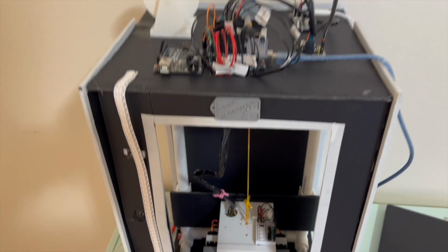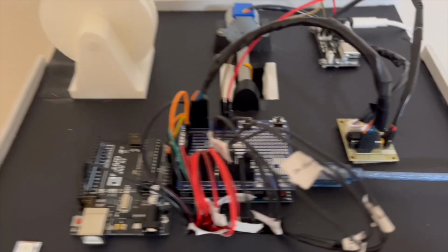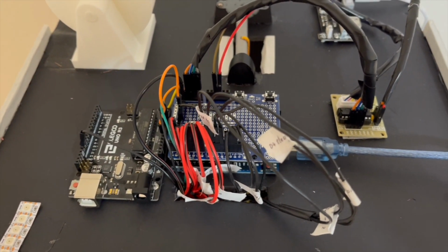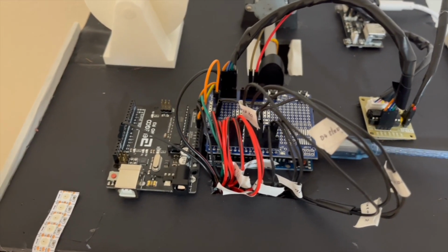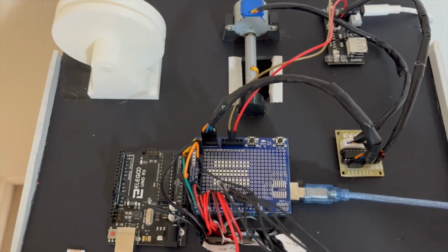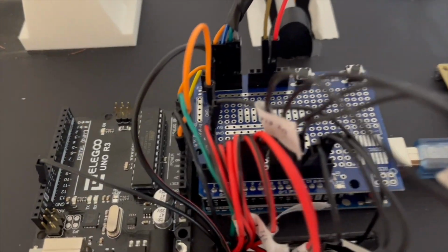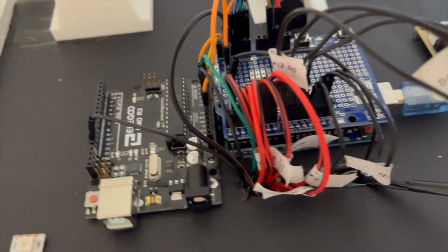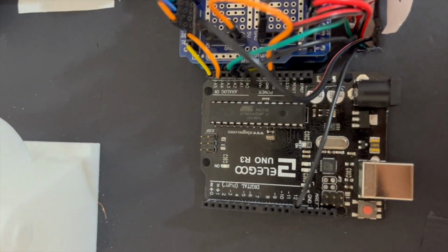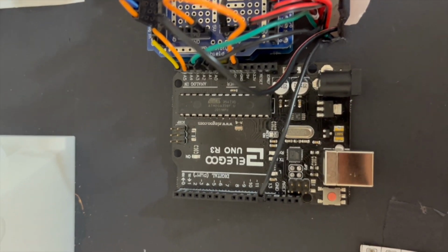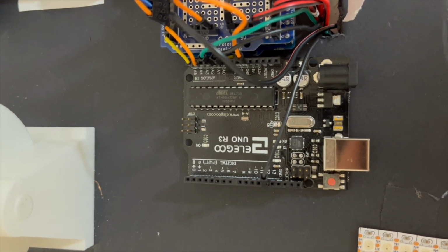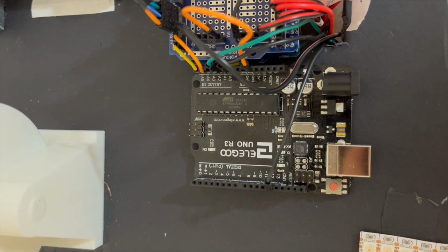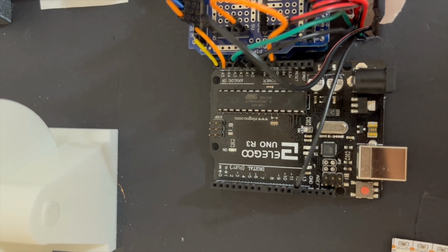Our elevator system uses two Arduinos. On the main Arduino, floor buttons are connected to pins 2 to 7, elevator indicators to pins 8 to 11, and servos to pins 12 and 13. The second Arduino communicates with the main one through analog pins A0 and A1. It also includes a switch connected to pin 12 located on the lower back section of the elevator.